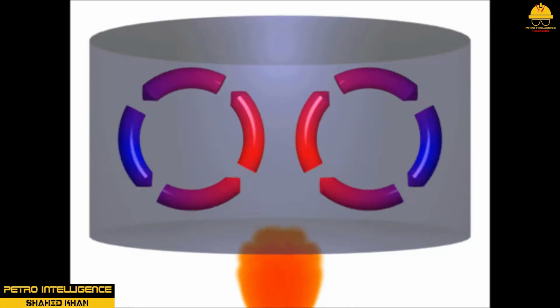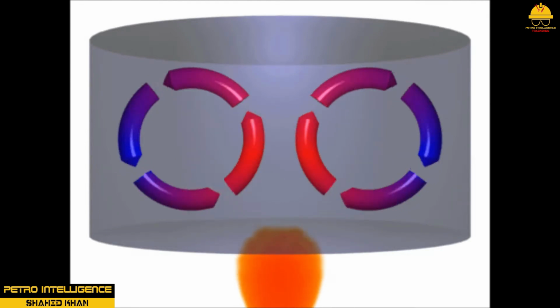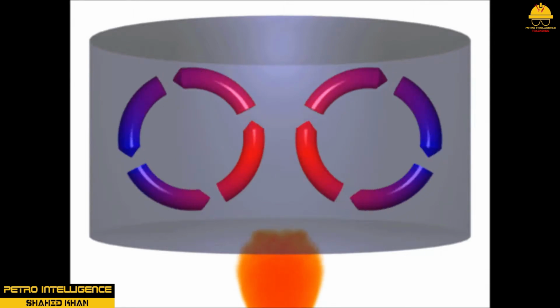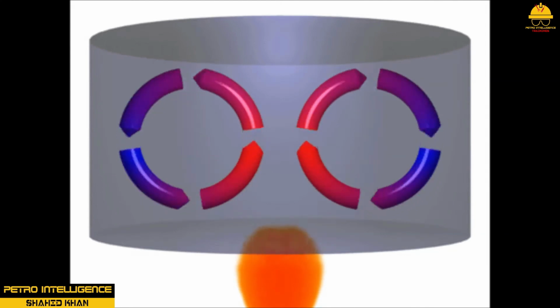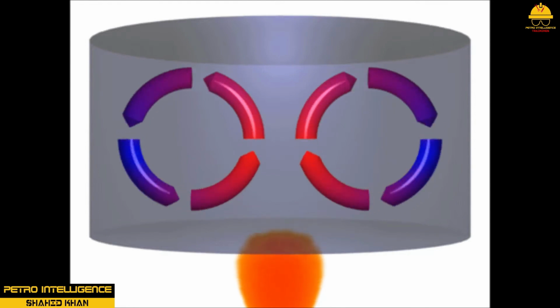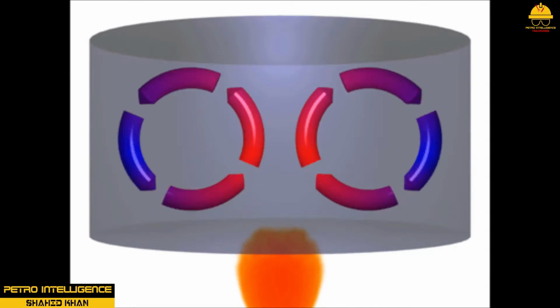Convection. Convection occurs in fluids when warmer molecules move toward cooler molecules. The movement of the molecules sets up currents in the fluid that redistribute heat energy. This process will continue until the energy is distributed equally. In a heat exchanger, this process occurs in the moving fluid media as they pass by each other in the exchanger. Baffle arrangements and flow direction will determine how this convective process will occur in the various sections of the exchanger.